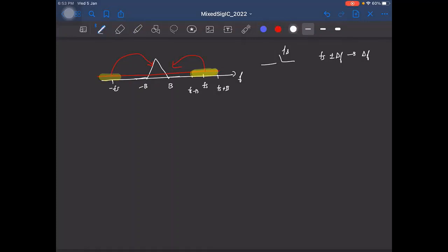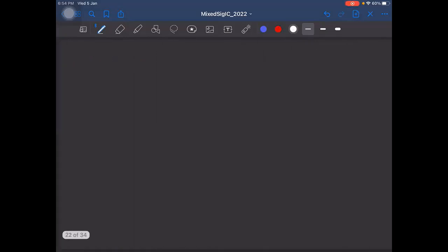And what was the solution to this? Well, we decided that we'll put a low pass filter, which was called the anti-aliasing filter, before sampling at Fs. And what should this anti-aliasing filter do? This should make sure that the noise that is getting folded back from high frequencies is attenuated to the required value. Okay, and this is where we had some problem. So let's see what that is again.